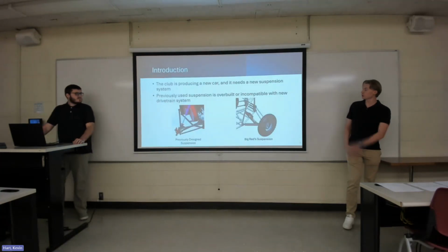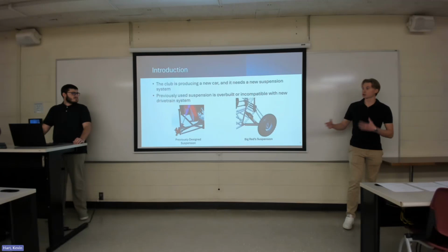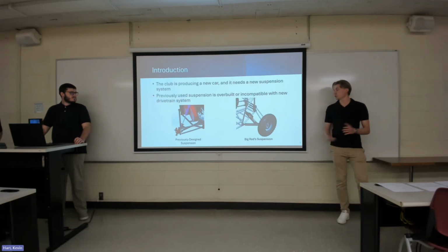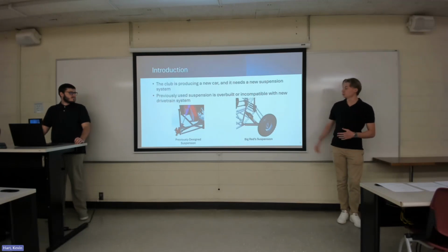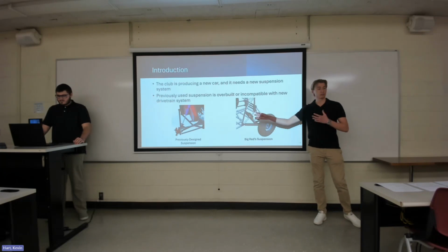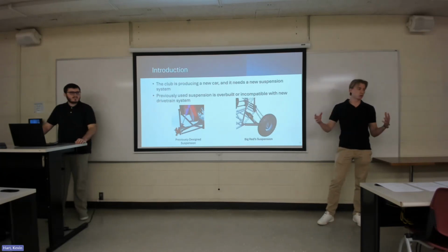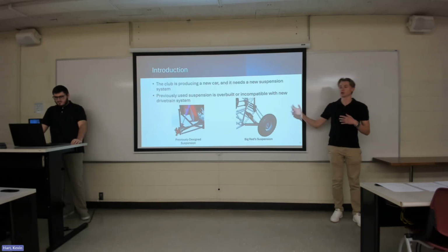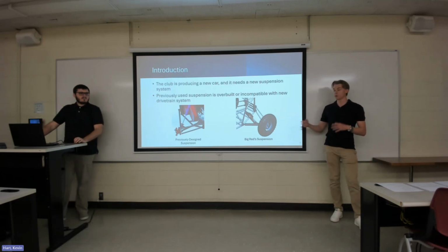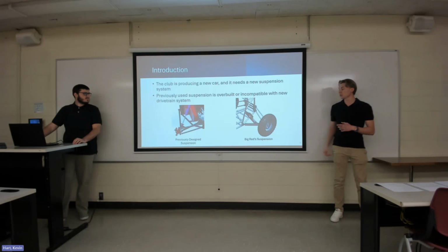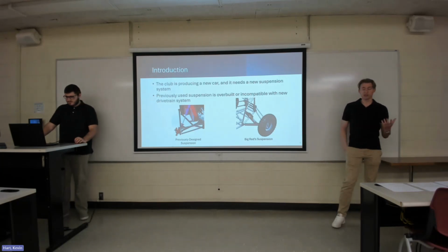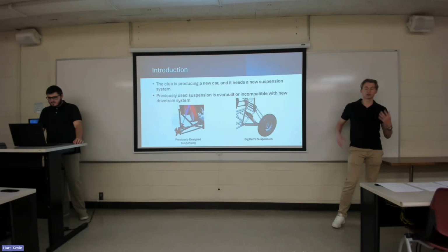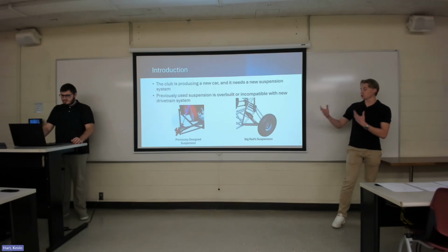So to introduce you guys, this year we're creating a new chassis. The whole Baja team has already designed a new chassis, and that includes an interim suspension design that incorporates the old style drivetrain that we were using with CV axles. One of the key aspects the drivetrain team wanted to revise is incorporating a load-bearing axle setup with U-joints instead of that CV axle assembly. So that's one of the key aspects of our redesign, that we wanted to incorporate their contribution to that.